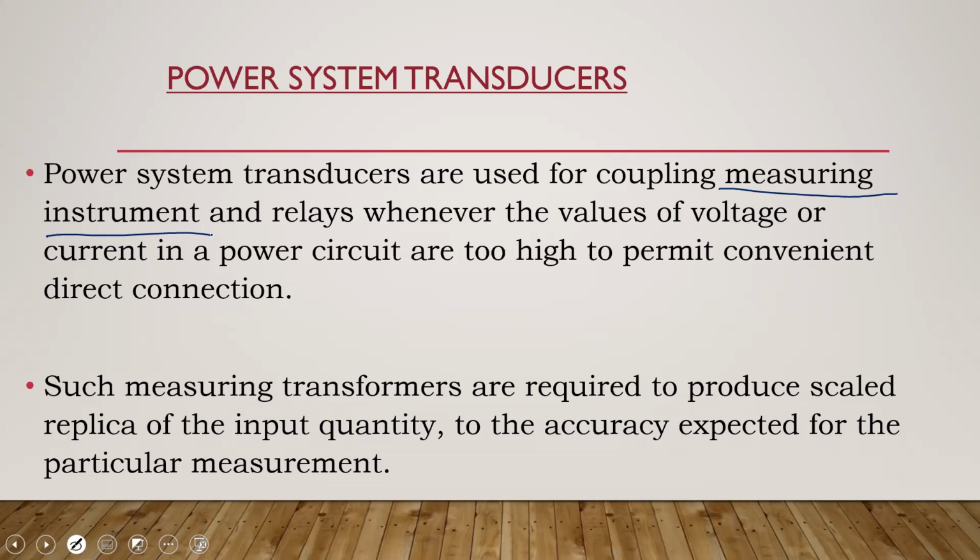Because remember, in the substation, I'm using Jamaica as reference, you're going from 138 to a minimum of 24 kilovolts. Yes? Your PT is taking it from 138 kV to 110 volts. That's significant. So your PTs are usually very expensive and are very large.